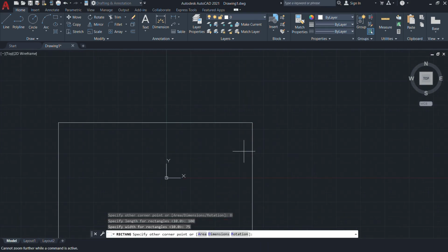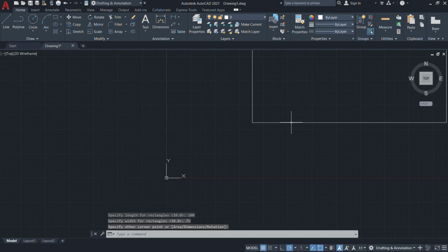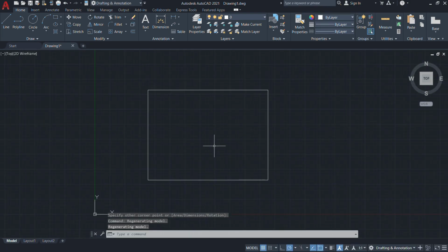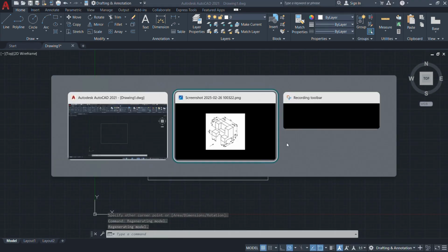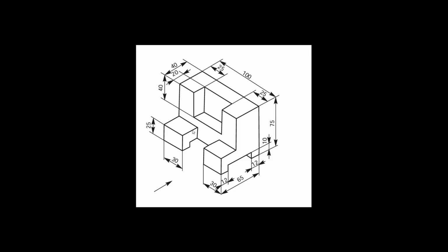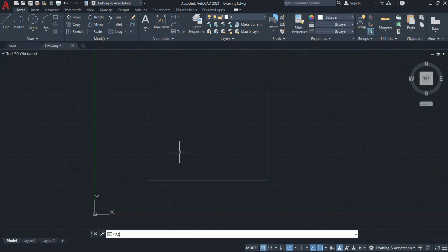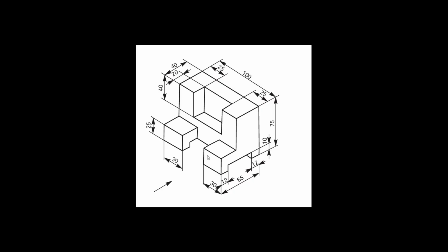Once we draw the profile, next I position it at the top end of this quadrant area. The overall rectangle profile is clearly drawn at the particular location. Let's draw the rest of this portion, that is the pocket area on the front zone as well as the bottom zone. First, choose another rectangular profile. Start from this particular zone. Here, if you see from the front zone, we are only able to draw one rectangular profile at the particular end. So choose this right corner end and draw a rectangular profile.